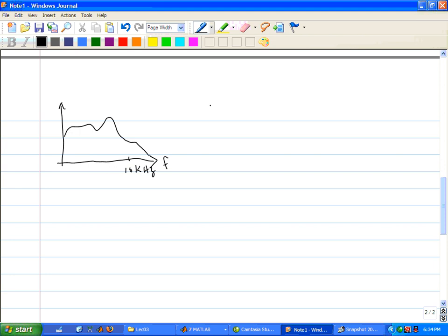So what I'm going to do is, actually let me draw it on top of the same axis. So I essentially have two options. So now the black is my signal, the red's going to be my filter. And remember, when you're looking at the frequency domain, I'm going to just do a multiplication of the information in the signal with the filter to get my result. So ideally, what I'd do is I'd build a filter that looked like this. Right? That's the perfect filter, because everything at less than 10 kilohertz remains perfectly as is, and everything above 10 kilohertz completely dies out. And if I do that, my sampling rate can be 20K.